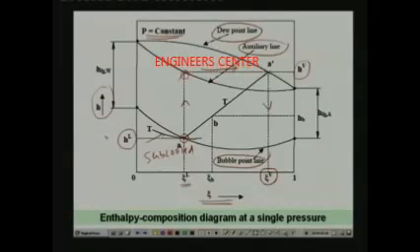What it means is that at this particular condition, saturated vapor of this mass fraction and this enthalpy is in equilibrium with saturated liquid of this mass fraction and this enthalpy. So, that is how you have to find the saturated vapor enthalpies and mass fractions.